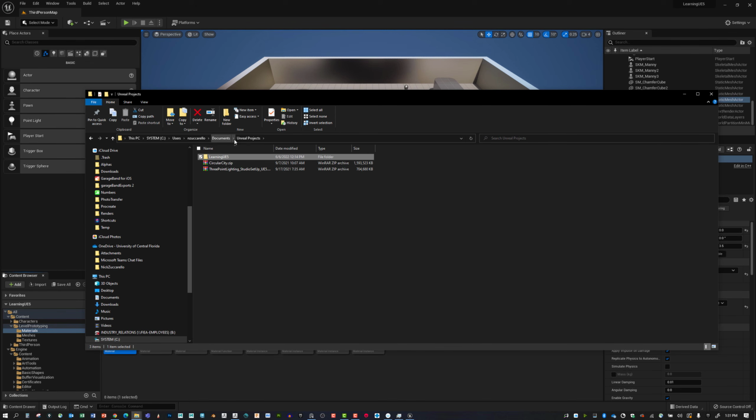At the beginning of this, I just made a new project called Learning UE5. It makes this directory structure for us. We've got config files saved, and that's the different settings for the engine. But the thing that you're probably going to be concerned about, if you want to transfer this information from one project to another, is the content folder. It is possible to move things that you're making from one project to another by keeping things consistent with this content folder.